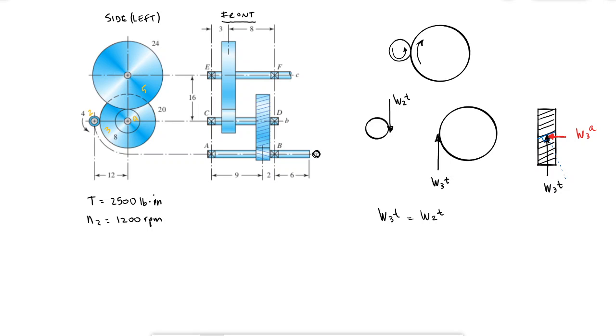And because there's a pressure angle, the dashed blue line is not the actual total vector; the actual vector is coming out of the page of your screen. It's like in 3D going into the page, and the angle formed between the 3D vector and the dashed line on the sheet of paper or your monitor is the pressure angle.